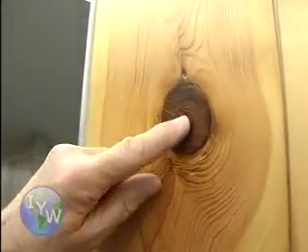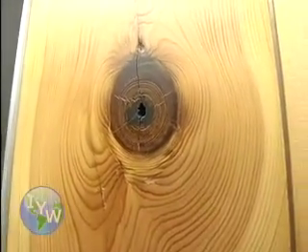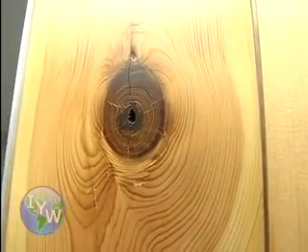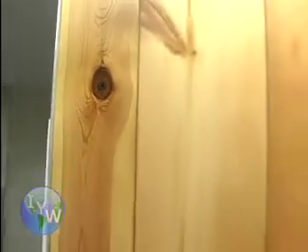If we would cut this at a right angle, we would have a round knot, where now we have cut a cross-section through the branch, and we have a round knot, so it takes up a smaller percentage of the strength. So in our softwood trees, we always have knots present because we use them structurally and we use the whole tree. When we get to the hardwoods, we don't like to have any knots present because when we make furniture, we don't like to have any knots.